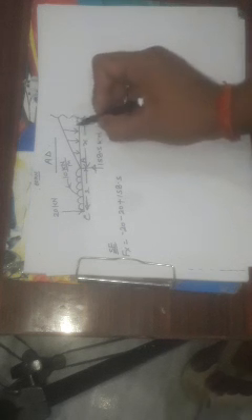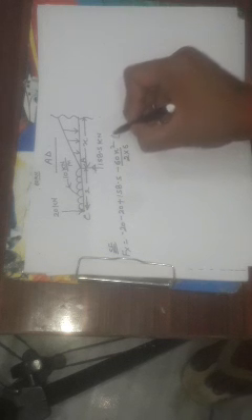Already we have covered it in a previous lecture. The total weight of the section of UVL is Wx squared upon 2L. So W is given 60 kilonewton per meter, so 60x squared upon 2L. L is the length of the UVL. The length of the UVL is given as 6. The variation is parabolic because the power of x is 2.